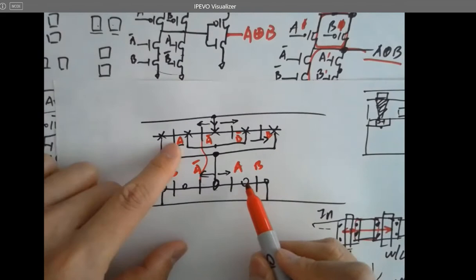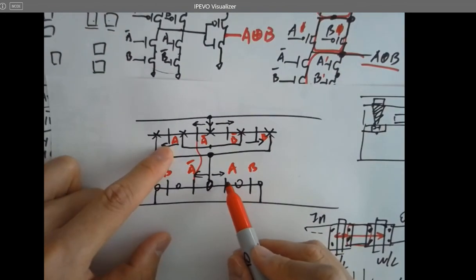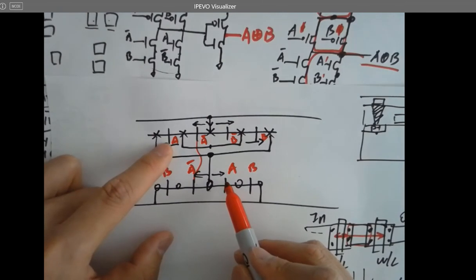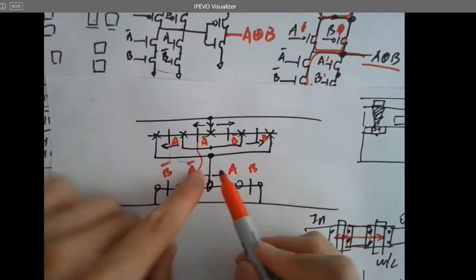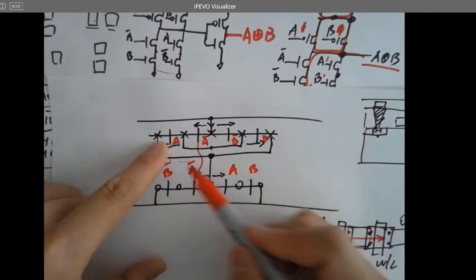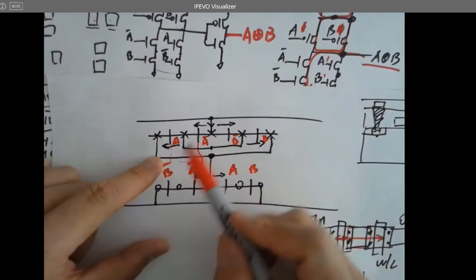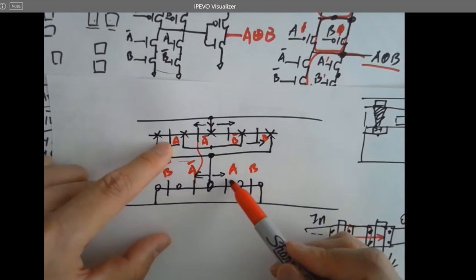What about these two? Have to think about it, right? Why? If you introduce a polysilicon, it's going to short with this poly. Even though, I know it's not a huge circuit, so if you directly use a polysilicon, it's fine because it's not really long, far away from here to here. Okay.